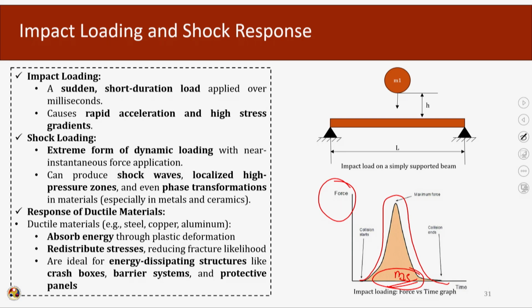Shock loading. This is an extreme form of dynamic loading with near instantaneous force application. It produces shock waves, localized high pressure zones and even phase transformation in material. Especially in metals and ceramics, phase transformation can occur due to the application of shock loading. And this phenomenon can be used in different applications. So, using shock loading, instead of doing it in the conventional way, different types of applications can be done.